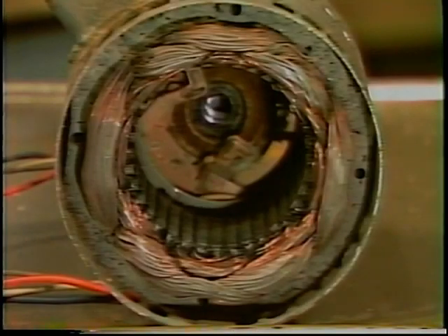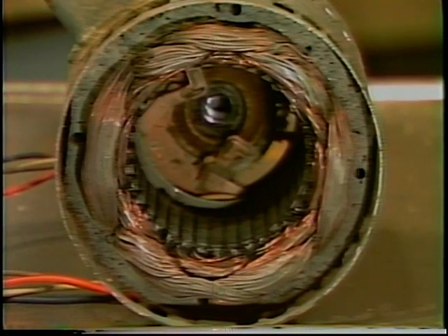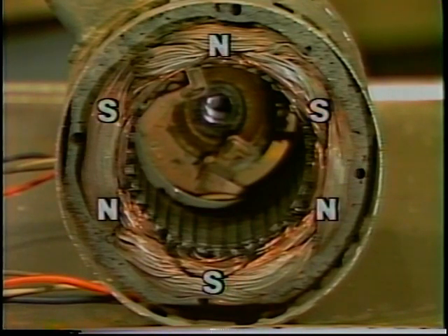An AC motor which can run at more than one fixed speed makes use of this principle. When you set it to run on a different speed, the switch connects the individual windings in the motor for a different number of poles. For maximum speed, the motor is connected for the fewest number of poles. Reconnecting the windings for twice as many poles cuts the speed in half. Three times as many poles produce one third the speed, and so on.